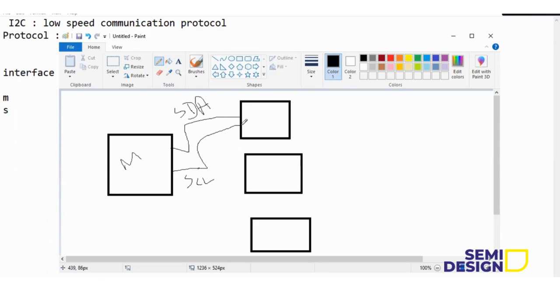At every cycle of the SCL, the data transaction will happen. Each bit will be sent at the positive edge of the SCL. That's how the 8 bits will be sent serially. Next, what is the mechanism by which the slave is going to store this data? The slave will have a shift register. It will receive the input data from the SDA and go on shifting the received data into the shift register.